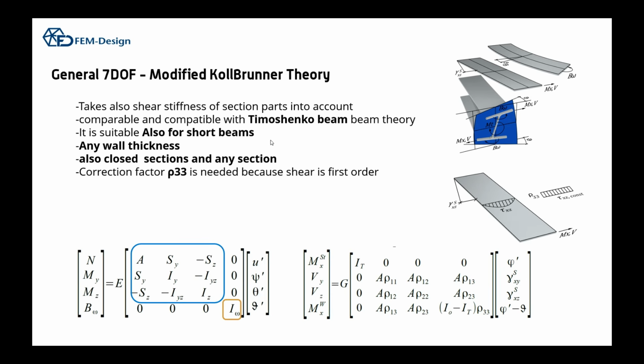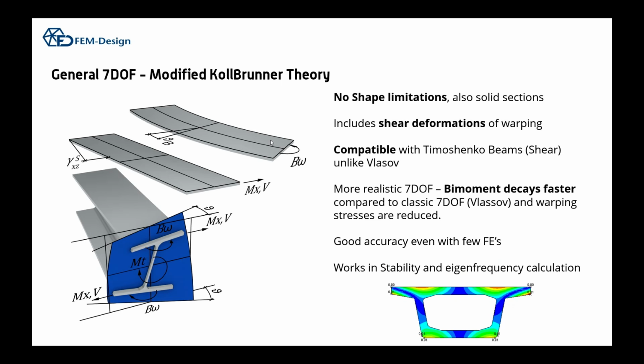And the good side is this is fully compatible with the classical Timoshenko beam. So if you apply it to any beam, no harm can be done. You get exactly the same results as with the 6 degrees of freedom beam model. So it's really handy.